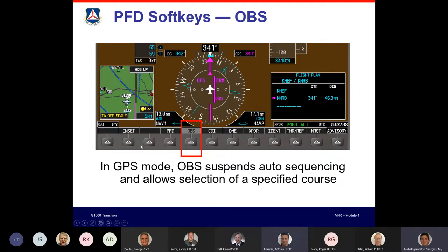Got it. And what if the approach only has a DME? In other words, what if it's not like in Oakland where you use the VOR for DME? What if it has a different channel specifically for the DME? I wouldn't be able to use it here, right?